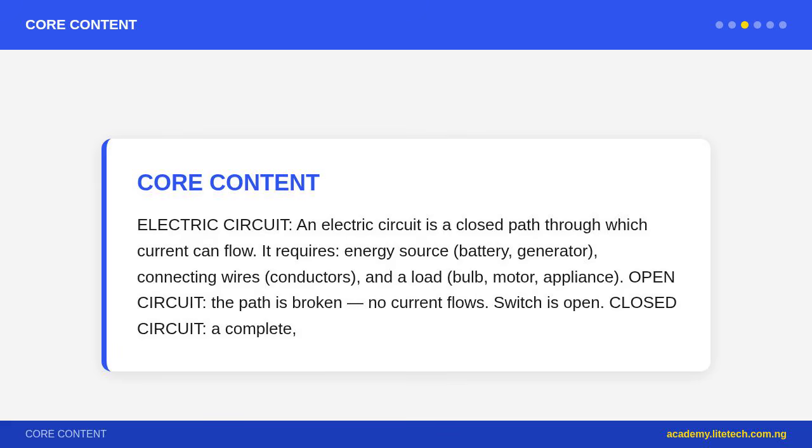Series circuit. All components are connected in one loop. Current has only one path. The same current flows through all components, all share the current. Voltage is divided among components. If one component fails, for example one bulb blows, all components stop working. Example: old-style Christmas tree lights, a simple switch controls all. Advantage: simple design. Disadvantage: failure of one stops all.